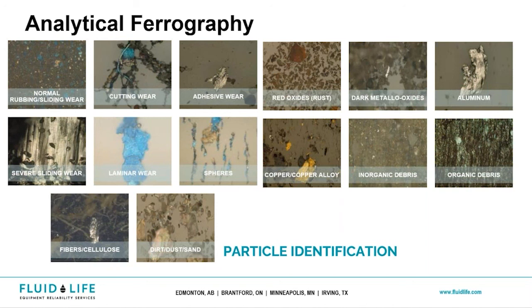So how this works is during the creation of a ferrogram, ferrous particles are going to deposit on the slide, and according to the particle size, non-ferrous particles and contaminants will also deposit. So knowing the nature of your abnormal wear and contamination in the lubricant is obviously pretty valuable. A maintenance technician can decide on a course of action, and you can adjust or optimize your intervals or your service type and scope, and you can deploy advanced systems to counteract what you would see naturally.